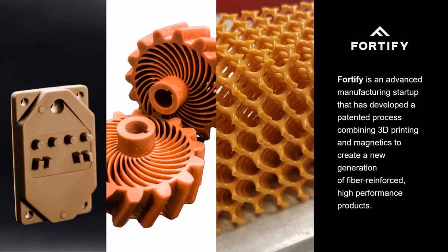So because of that, you're limited to the X and Y orientation for your fibers, and there are a lot of orientations that you can't do because you physically can't move the tool, the head, in that direction. So there are a lot of limitations as far as fiber orientation goes. In our case, we use chopped fiber. A number of those companies also use chopped fiber. Some of them use continuous fiber, and there are whole theories as far as the benefits of both of those.